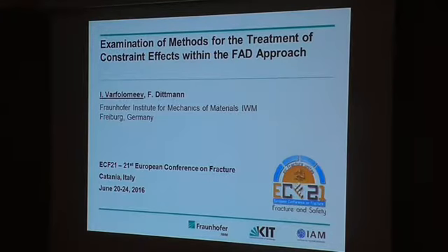Good afternoon, everybody. I'm going to talk about the application of the constraint methodologies for the assessment of components using the failure assessment diagram approach. So our main focus is on the methods which could help engineers to perform quickly and safely the failure analysis using the results which have been derived so far.